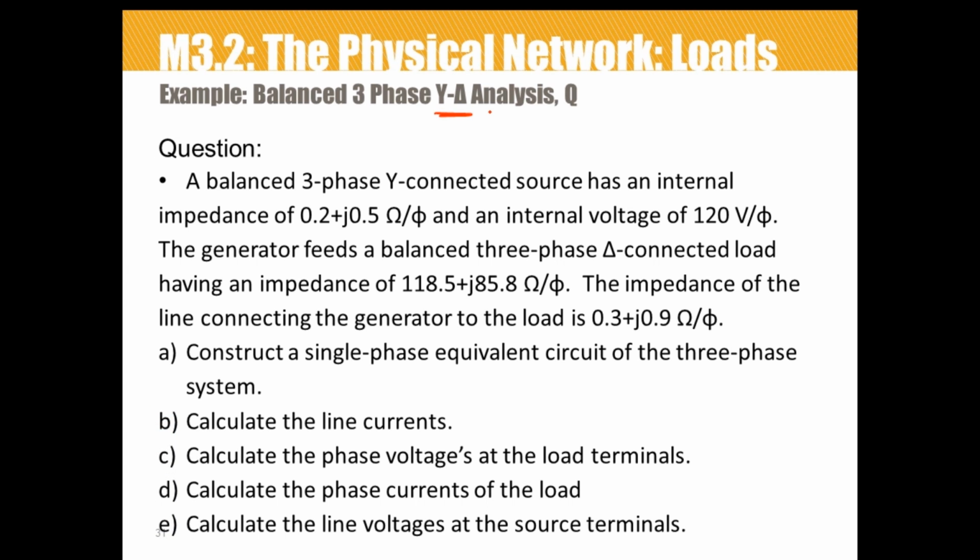analysis. Although you can use KVL and KCL to perform this analysis and you'll get the correct answers, the easiest technique is to use the delta to Y transformation that we just talked about. Anything that's connected in the delta form, you convert over to its Y equivalent, replace that in the circuit, and do the analysis. You can read for yourself what the problem statement is. Pause while you read this, and then continue on to the analysis that we'll perform on the next slide.